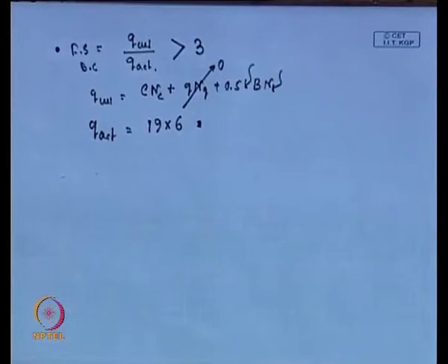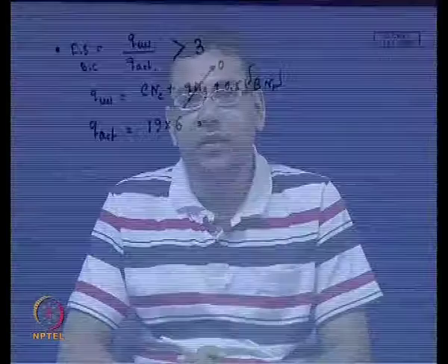So, we can see here based on the internal stability, we have to determine the spacing between the reinforcement and the length of the reinforcement, as it is not uniform throughout the depth of the reinforced retaining wall. So, we have to make it more economical, so that at different depths we can provide different spacing and length.